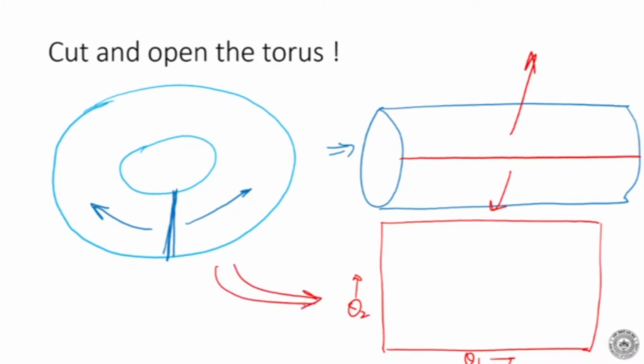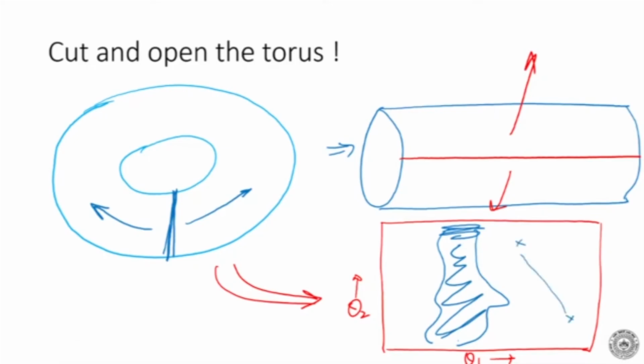Again, this is my C space. It is not Cartesian space, but it looks like Cartesian space. Here it is easier to visualize. Say, for example, you have an obstacle, and the obstacle is something like this. It has some funny shape. This is my obstacle. Then I can do path planning. I want to go from here to here. I can do path planning like this, because the robot has become a point, and in my configuration space this is now my obstacle. So this is obstacle space and this is free space.